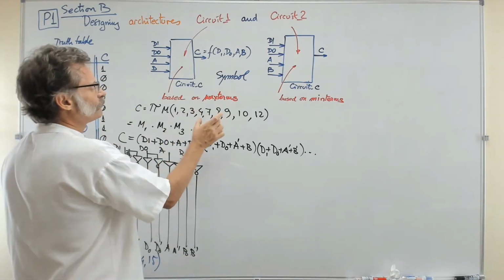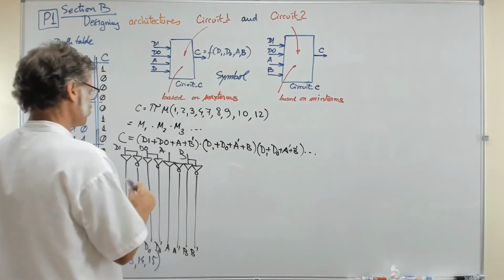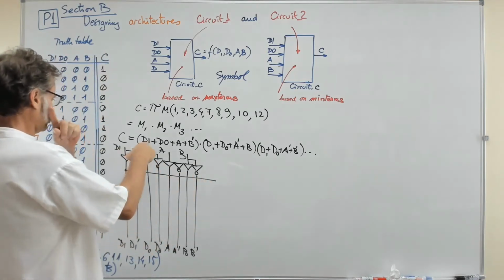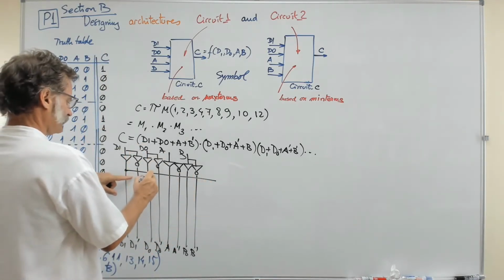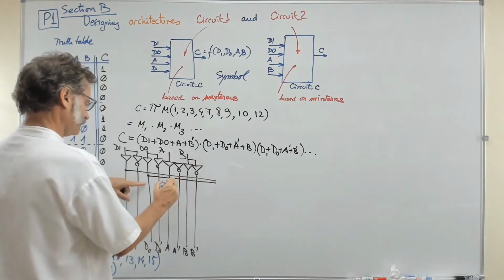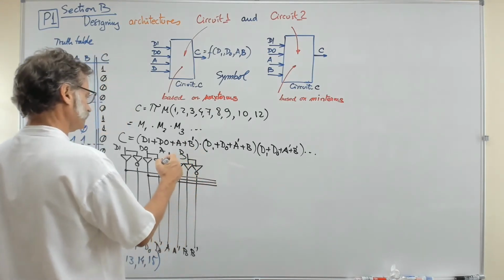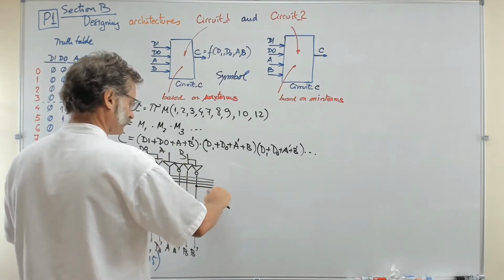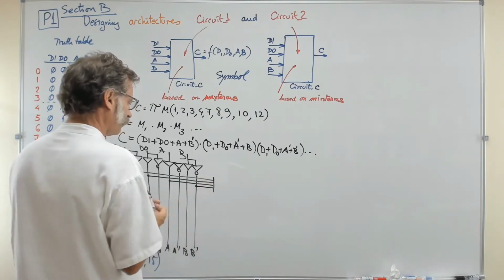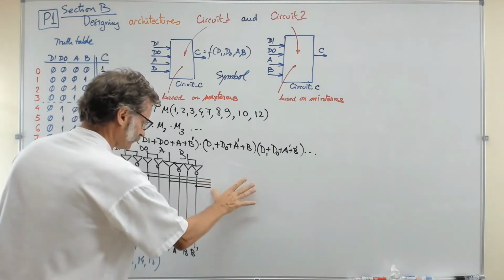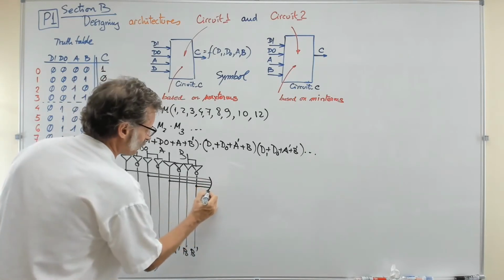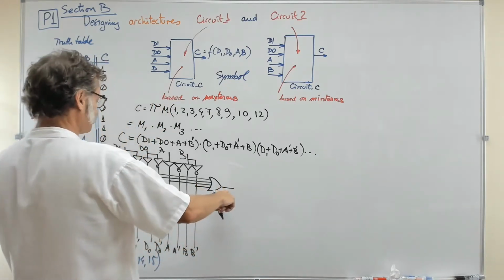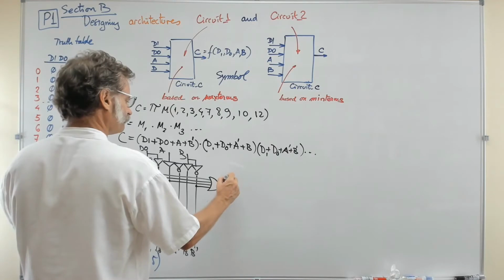So you can go composing the maxterms simply taking the minterms this way. You see, this is the D1, then you connect the D0, and then you connect the literal A, and finally the literal B naught, which is that one here. In this way, you can connect OR, right? Not an AND, but an OR. So just draw the OR, and that is a wire that can be very well named maxterm 1.